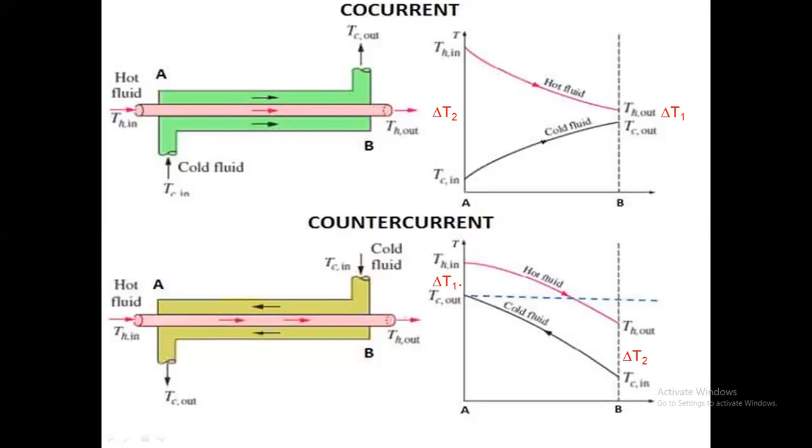So in terms of the number line, which comes first, it's 1, then followed by 2. So in terms of the delta T, counter current is delta T1 in here, and you have delta T2 in here. Then just simply memorize that in the co-current scheme, you have delta T2 here and you have delta T1 in here. Okay? Counter current is more efficient than parallel flow.